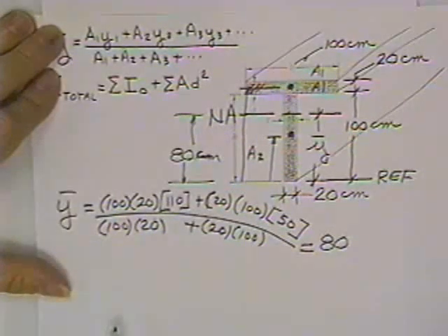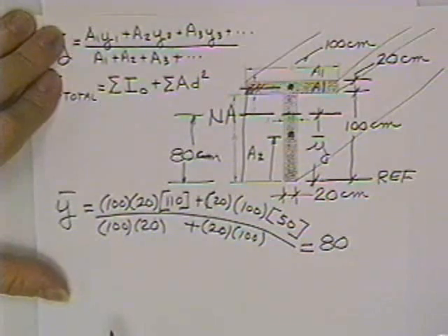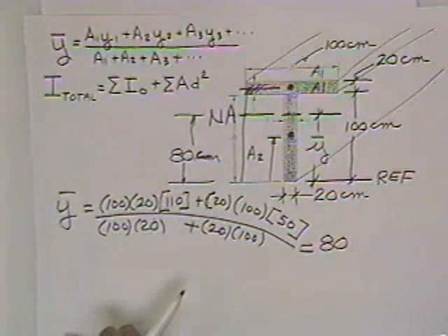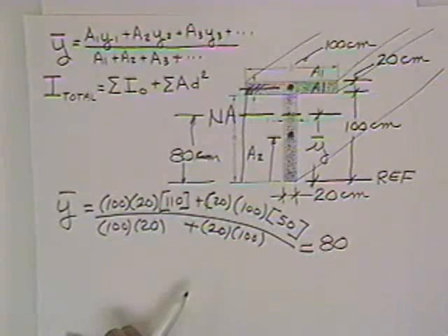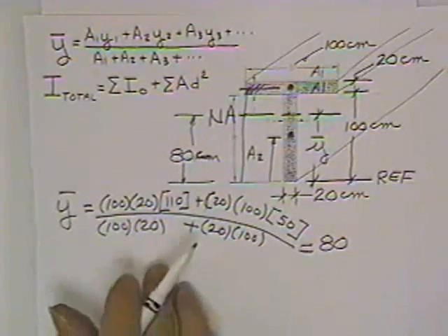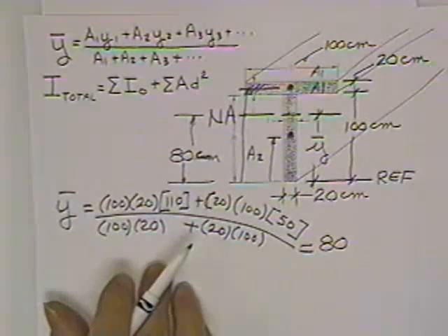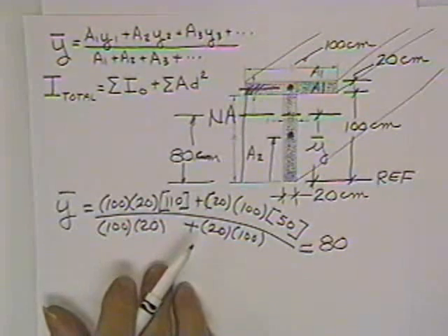Now, all areas have a moment of inertia just because they're there. All they got to do is just be. They get a moment of inertia. The list of the magnitudes of those moments of inertia in your reference manual are on page 25, 26, around in there. Now, they will give you moments of inertia about some rather strange axes, but the only ones you really need when you talk about bending of beams is I about the centroid, and that'll be shown in the book as I sub xc.